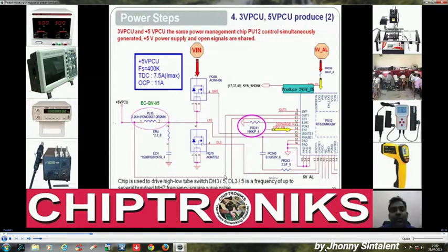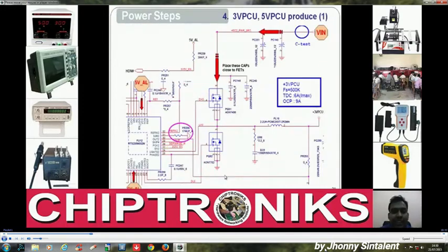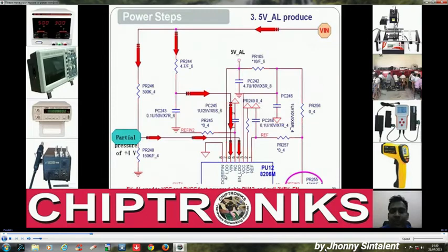Okay, so till now we are clear with the steps. Let's again see these steps over here. VIN is coming over here at pin number 6. Then this VIN is divided through the resistance divider going to the enable LDO. It gets enable LDO, generates the LDO marked by 5V underscore L.